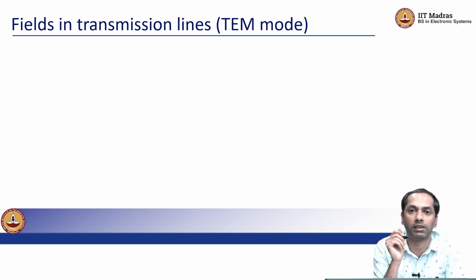But in the discussion for parallel plate waveguides, I did mention that there can exist a plane wave at grazing incidence launched into the parallel plate waveguide, and this happens only specifically for the TM injection, where the magnetic field is aligned to the y axis and the electric field is in the z axis.